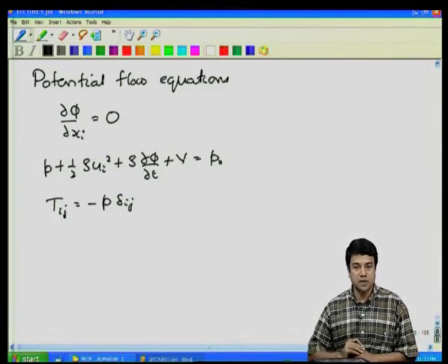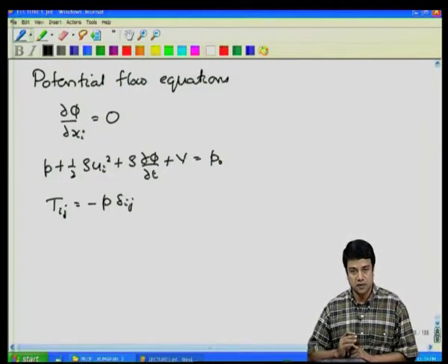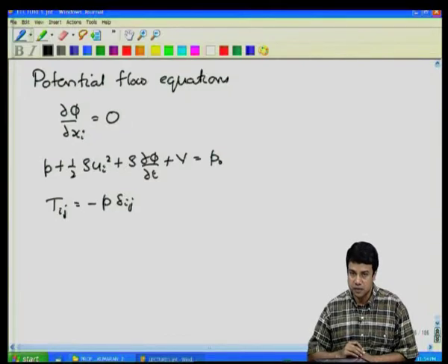Therefore, you have two velocity boundary conditions at each surface, no slip condition or 0 stress condition or some constant stress condition. When we neglected the viscous terms, we neglected this highest derivative, and therefore, we can no longer apply all the boundary conditions that were there in the original problem.